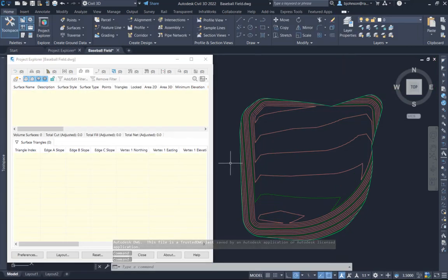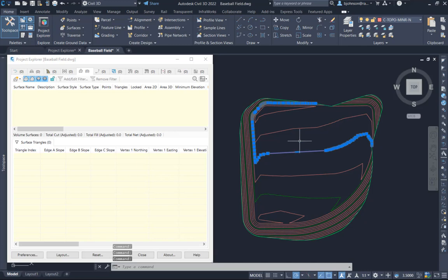So at the end of that process, I do have a new AutoCAD drawing with polylines that represent the contours for my surface. The results of exporting to an AutoCAD 2D drawing file are AutoCAD entities such as lines, arcs, and polylines, depending on the object that was selected. Text from labels such as alignment labels will be exported as mtext in AutoCAD blocks. Corridors also have a unique feature that allows you to filter specific baselines and feature lines.